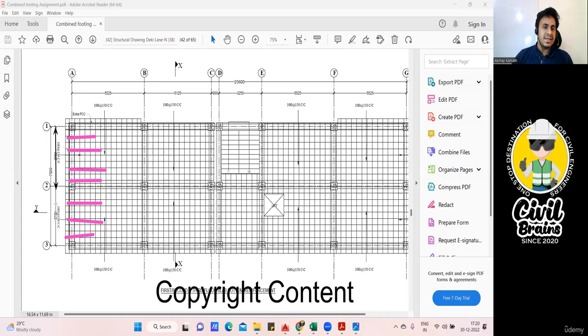And this distance, luckily or unluckily, is given from center to center, but we need it from clear span. So 7500 is given, minus half beam from here, minus half beam from here. Again, minus the center beam. You're able to understand, no? In the center, we are not putting any bar, so this center span also I need to deduct. Simple. 7500 minus 150 from here, minus 150 from here, and minus 300 from here.